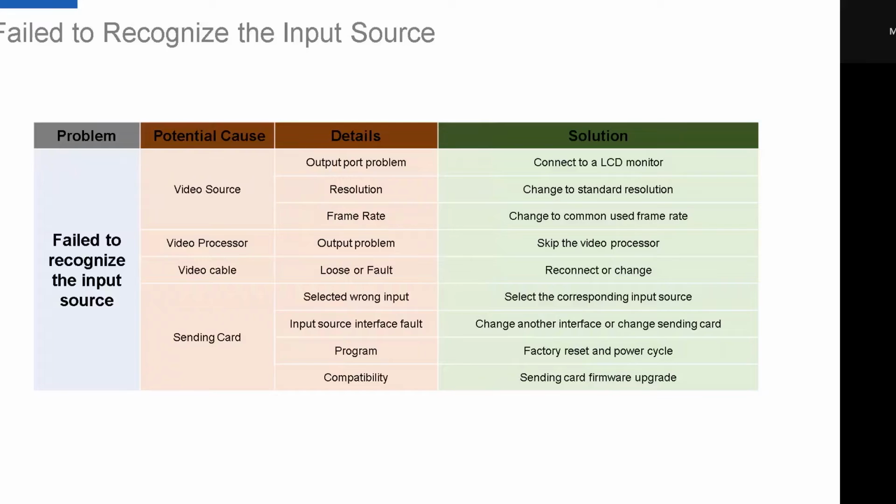How to do that? Just connect your video source to an LCD monitor. Make sure the monitor can see the video source successfully. If it's not, we can say this is the output port problem of your video source. You may need to change to a different video source. But if the video source is connected to an LCD monitor and can be recognized perfectly,